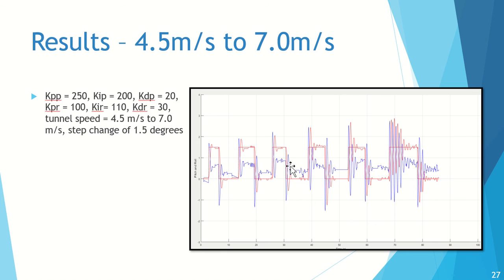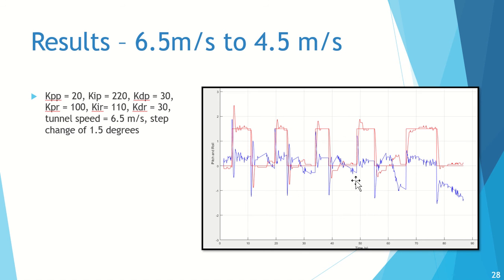So you can see if you have a fixed gain at low speed and use it at high speed, you'll get into performance problems. So you can't have one gain that works across the tunnel. So you could investigate all of these features and then design controllers that will give you good performance at low speed and good performance at high speed.